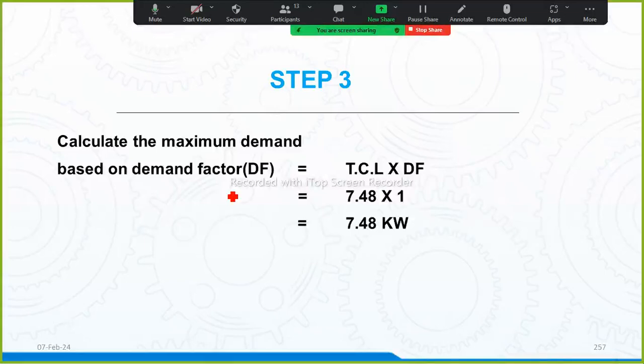Why? Because whenever there is a power cut happening in a room, we are not giving all the lights and all the fans in the UPS. We are giving only limited loads. Like if suppose in a room we have 4 lights and 4 fans, we are not giving all 4 lights and 4 fans on the UPS. At least we'll give 2 lights, 2 fans and 1 socket on the UPS, so that it's an emergency supply. Whenever the power cut is happening, that should be working.